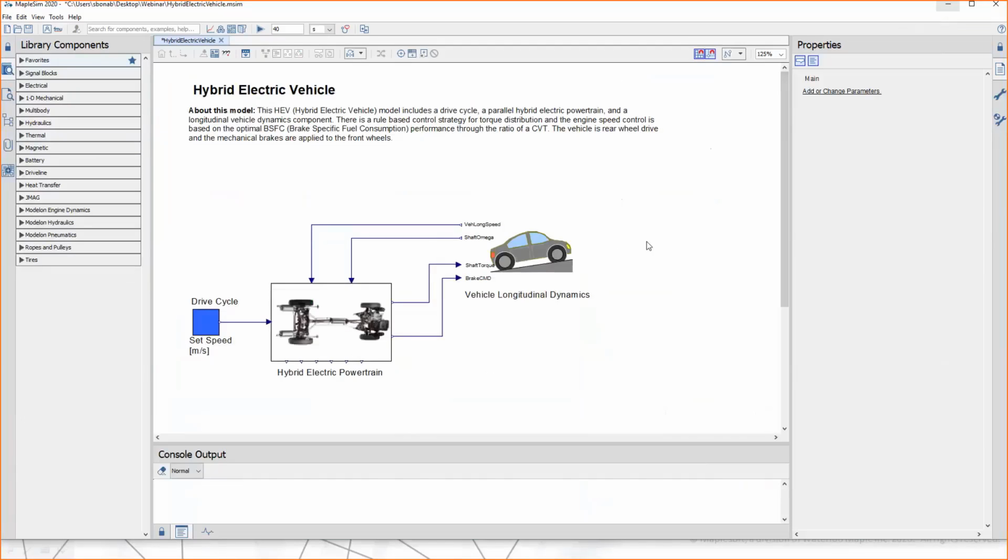So as you saw, for the first pass of my analysis, I had used longitudinal vehicle dynamics. But let's see what can be achievable by integrating MapleSim to Adams through FMU, FMI technology, through functional mockup units. I want MapleSim to take care of the powertrain model and Adams of the vehicle dynamics, so that I'd be able to run my powertrain against the full-fledged 3D vehicle dynamics model.